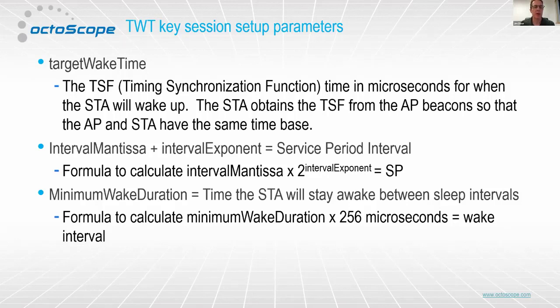There's a minimum wake duration field, and the value there is multiplied by 256 microseconds. That will give the wake interval within the service period, and then we just end up with the remainder of the service period as the sleep time.